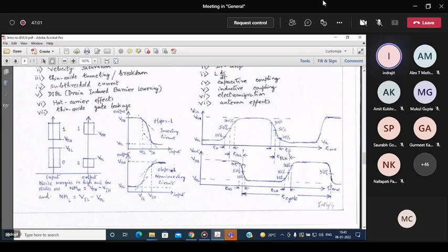That means how much time the circuit takes in response to a positive going wave. For an inverter, if you have a rising wave at the input, you get a falling output voltage at the output. So how much time the output takes to come down to the 50% point, starting from the 50% point on the rising input, is referred to as TPHL.